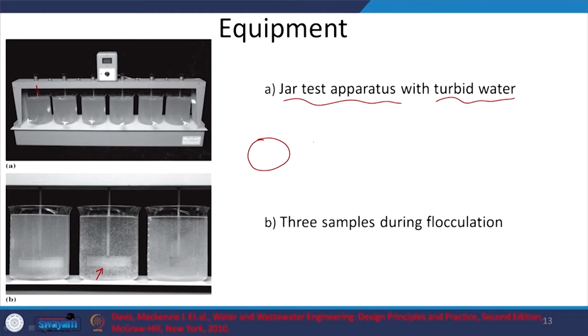But for greater turbulence, if you take square or rectangular ones, that's better. But in general, these are difficult to maintain, and the circular ones are easier to maintain. So that's why people use the circular ones. That's something to keep in mind, right? So you can see the flocs being formed and maybe later settling out. So different stages of coagulation and flocculation.